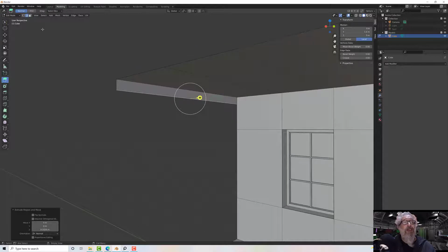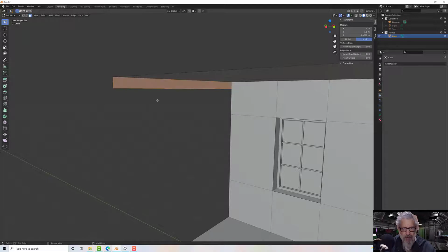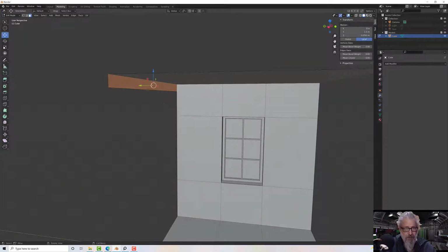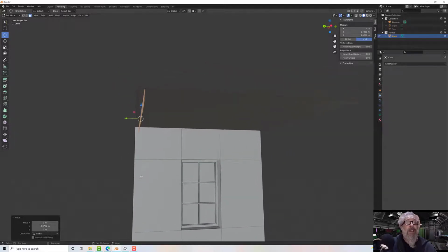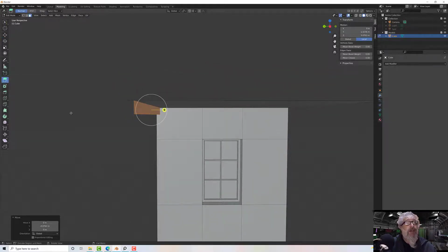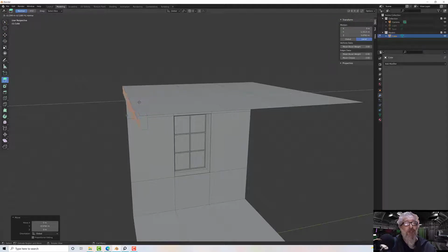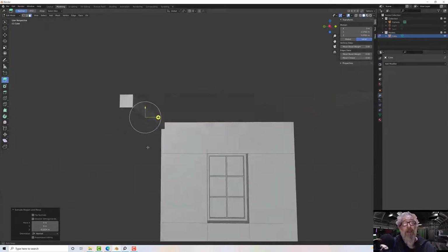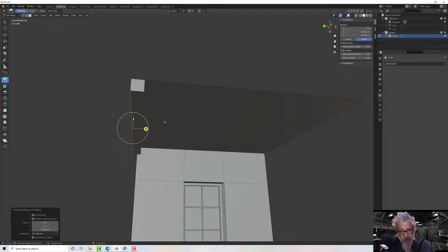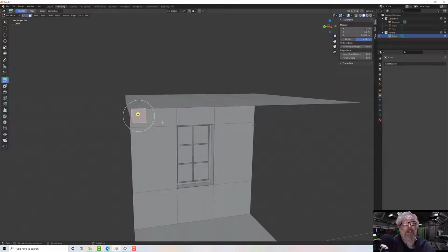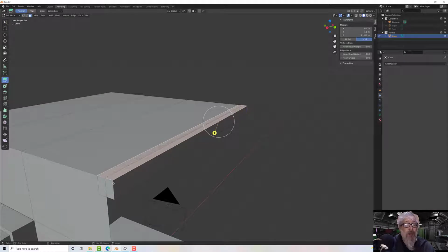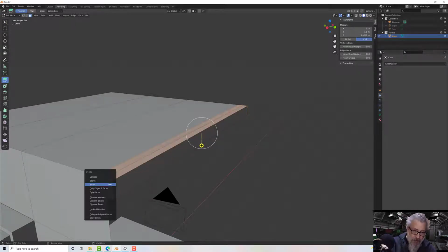And now I want to detach it. So if I select that polygon and press the Y key, that will detach it, and now I can move it 3 inches inwards. So it's -3 inches. There we go. So now we can use our extrude tool and extrude it in this direction 6 inches. So -6 inches. Now I've got a square beam, which is pretty good. That's what we want. But I don't need the top or the small front and back polygons, so I'm going to delete those.